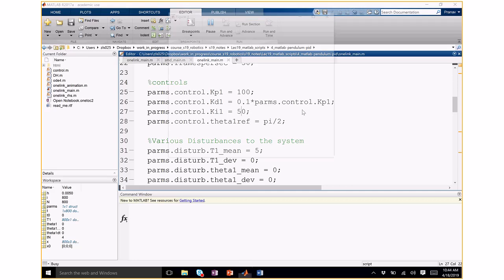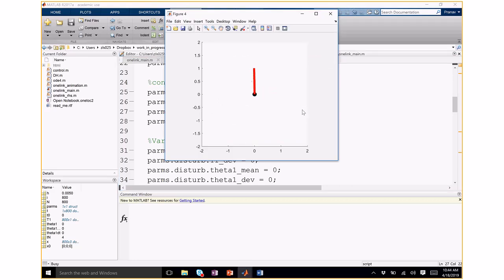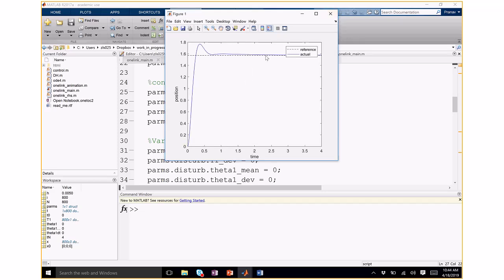So you say that this system is not critically damped because of what KD? The KD is 0.1 kp. I just put some number there, which is about 10. The actual value is more complicated than that. You need to have the control partitioning and you need to find the critical damping. It's not been done here, but you can easily program that. I already have code, which I showed you in the beginning of the class, where I do critical damping for the pendulum, in which case there was no disturbance. So it stopped. Let's see the errors there. See, it's almost 0. It works.